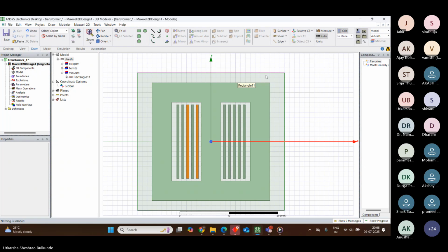In short, it can simulate for the whole page also, or it can simulate for just this much geometry. If it simulates the whole page, it will take a lot of time. If it simulates only this geometry, then we will not be able to see fields outside of this geometry.